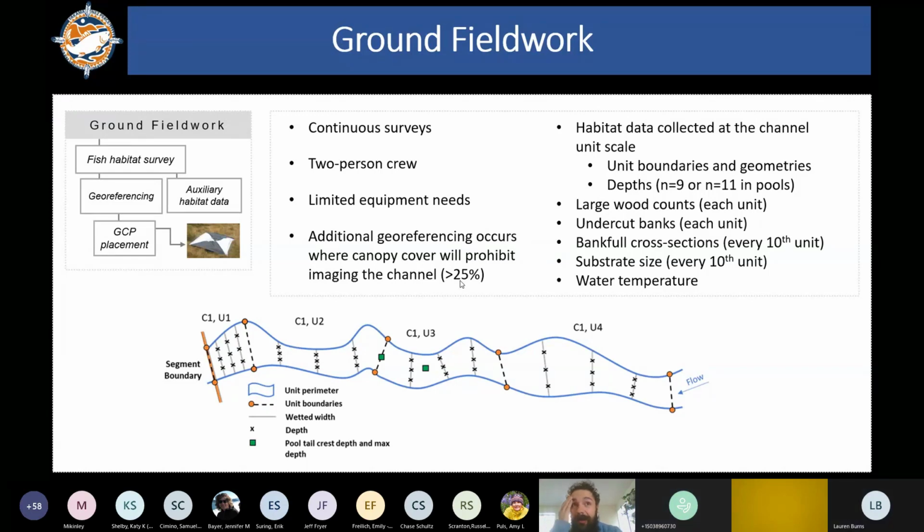Sure. Since UAS technology is so new, there's not a whole lot of opportunity to compare multiple acquisitions over time. But what we have done, like I mentioned in my presentation, is compare the digital surface model that we created from the overlapping UAS imagery to LiDAR imagery to see if we can estimate the amount of volume change that has occurred between those two time periods. And you can do that with NAIP imagery as well, or any other image source. But we haven't had a whole lot of opportunities where we can compare multiple UAS acquisitions over multiple time periods. I'm expecting that's going to change very shortly once the Forest Service has a fully operational UAS program.